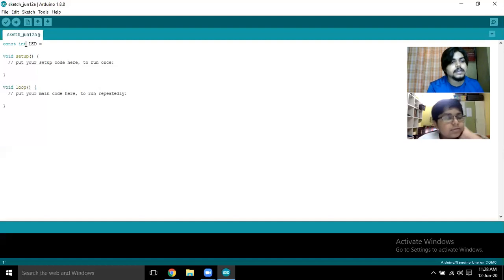So first of all, we are writing const, then we are writing int. I guess you know about int a bit. Int is a data type. Int, char, float are the data types. Int stores integers. Why are we writing it? Because if we are connecting to digital pin 8, then what is 8? 8 is an integer. That's why we are writing int over here, and LED is the variable which we are using, and the LED is connected to digital pin 8.